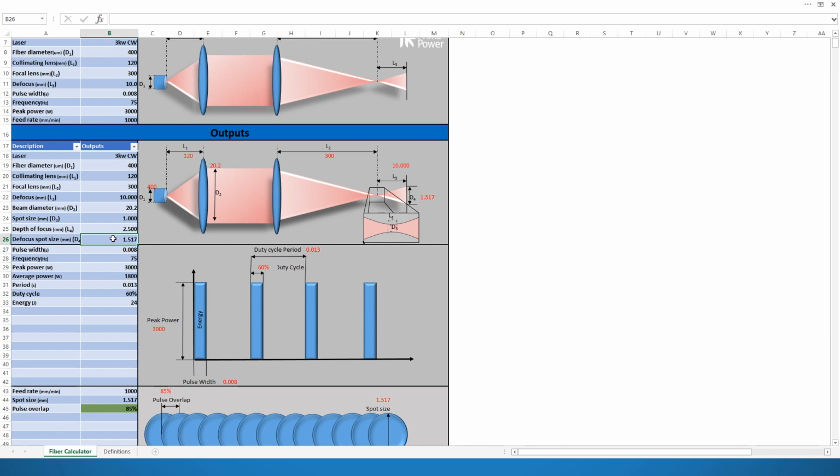Another very important consideration is the type of gas that we will be using, along with the delivery method. Given the requirements of this weld, I will use our Smart Shield weld nozzle along with a coaxial tip to deliver gas to the process. I will start by using nitrogen as our process gas, being delivered at around 70 liters per minute or 2.5 SCFM. With these parameters as a starting point, we are now ready to move to the machine and begin trials.